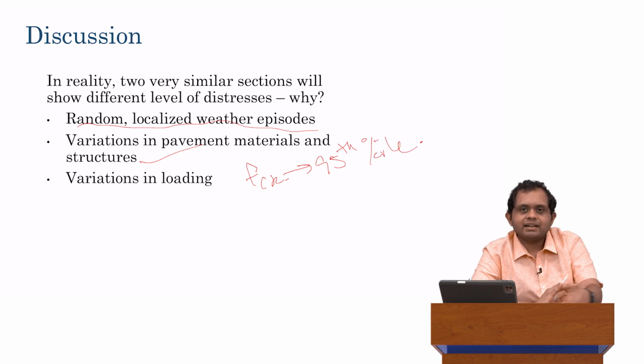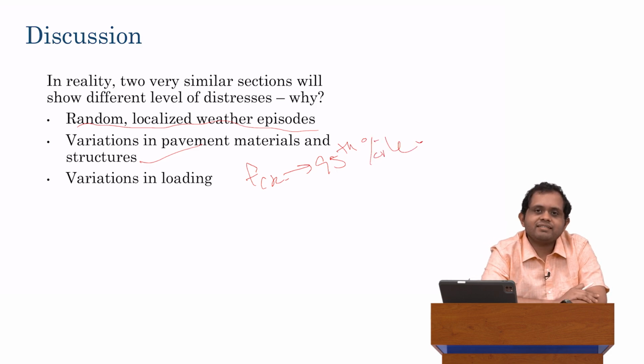So basically, if we take a number of specimens and we test them, and we take the 95th percentile strength of those results, then that basically is what FCK is. So what this should implicitly tell you is, for the very same mix design, if I cast a number of cubes or cylinders and I test them for the compressive strength, I will not get the same answer for all of them. This is what we would call material variability.